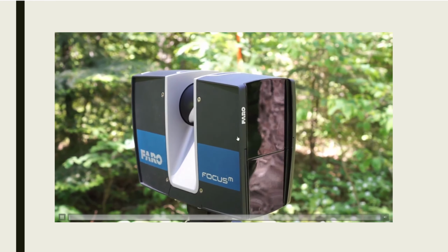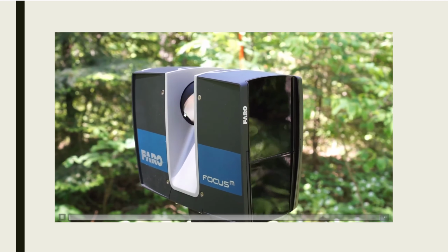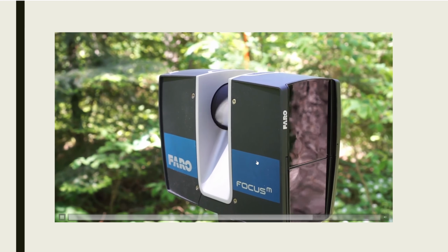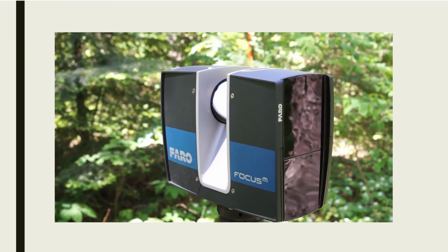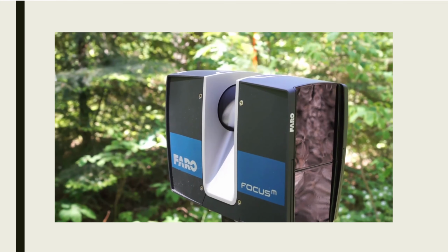What happens is the laser comes out of the unit here and hits that mirror, and the mirror spins. So imagine that this tool is taking a slice of the forest the width of a laser beam, and then it's slowly going to rotate 360 degrees and capture everything except for what's directly beneath it. This unit is a little bit slower. Newer ones are faster. There's trade-offs with this technology.